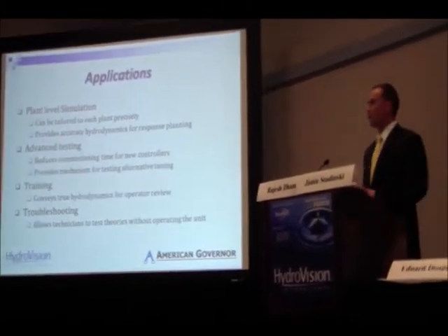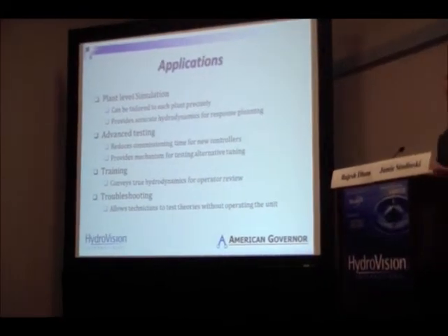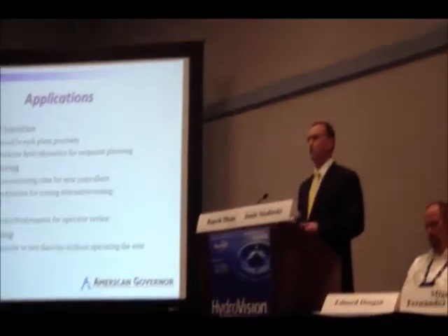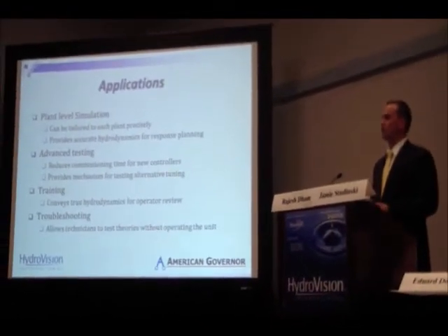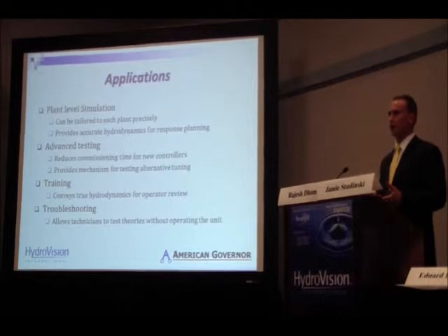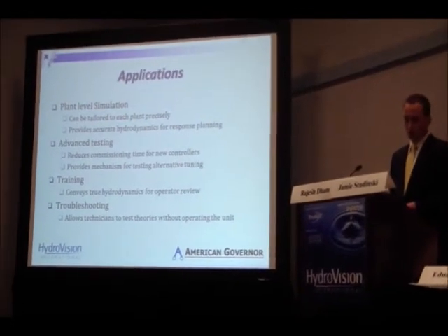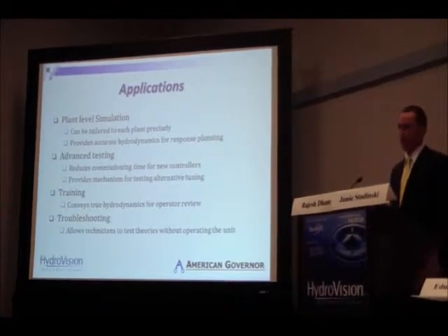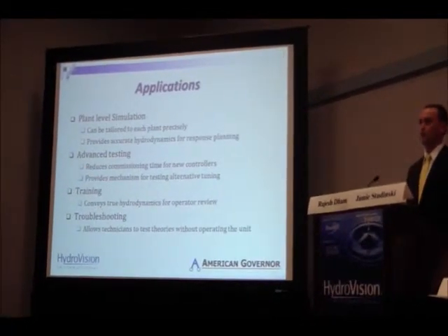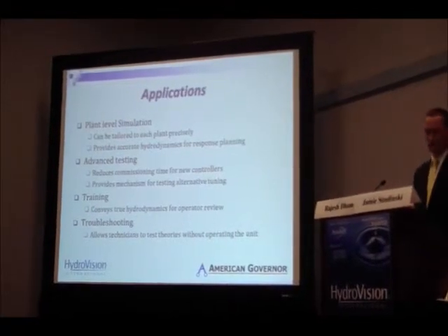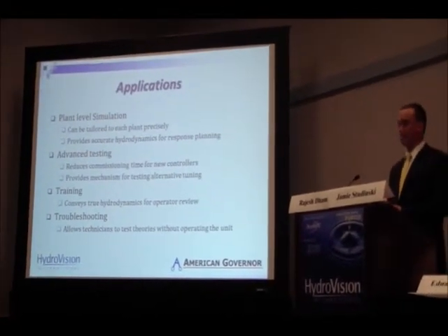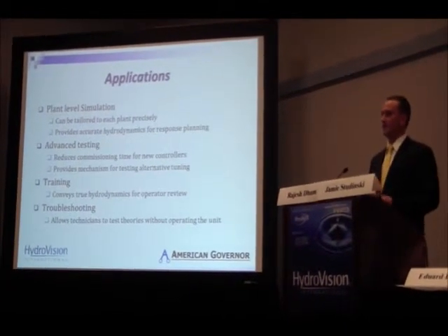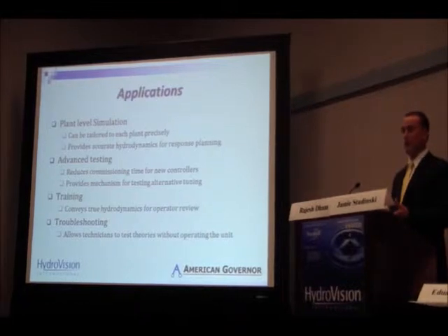So really, the cool thing about this whole process is that it's repeatable, and it can be really tailored to any particular power plant, especially pump storage facilities or other standard generating facilities that would incorporate some interesting hydrological components. We can take this sort of methodology and apply it to any given number of plants and provide any end user essentially the virtual version of their plant. This can be utilized, as we've done in this case, for hydrodynamic response planning. We can see what we need to do as far as PID gains, as far as our megawatt feed forward parameters, as we said.